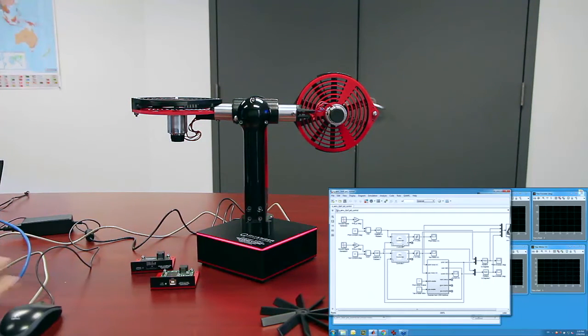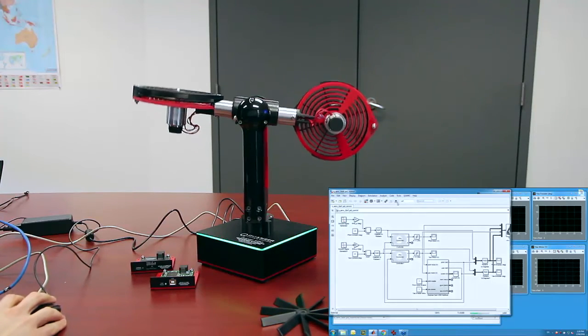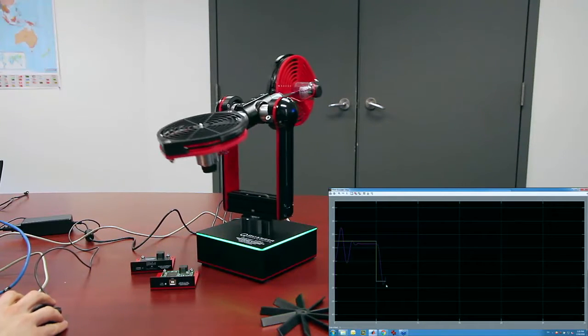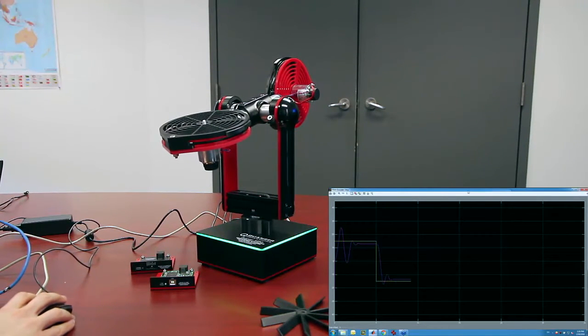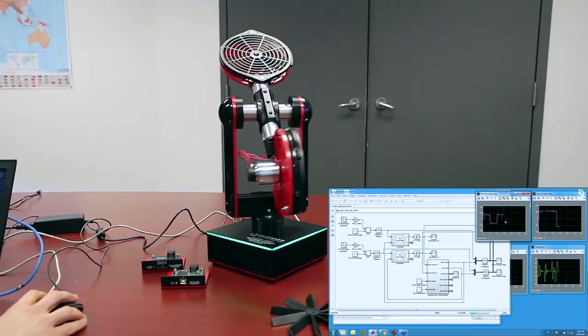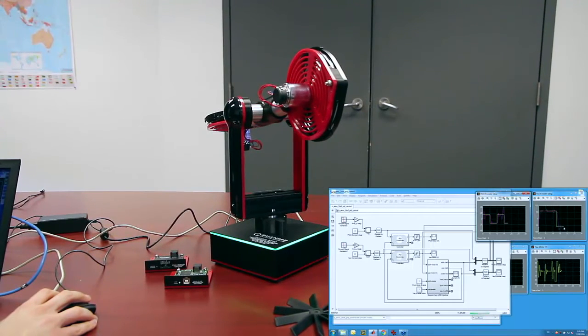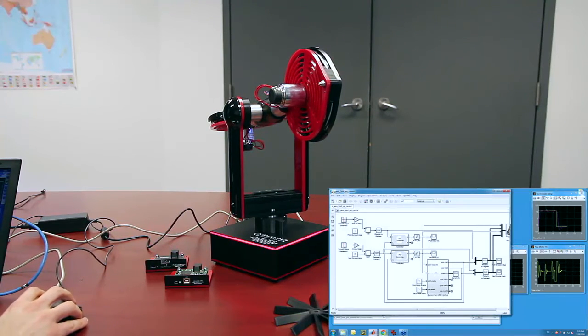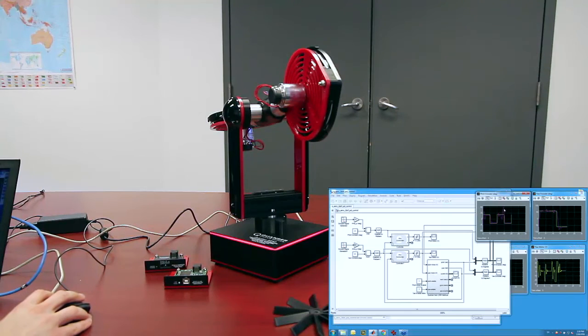So with the PID control, something to take note of is that when we do the control design, we consider each axis separately, right? So it's not a coupled controller, it's decoupled. Now I've got a set of gains in here, and I'm just going to go ahead and run it. Right now, the yellow here represents the set point, and the purple is the pitch measured from the encoder. Note that when it's changing in the yaw, which is a really big movement, I'm just going to stop this for a minute, then you'll see that in the pitch, you get a huge overshoot here, right?